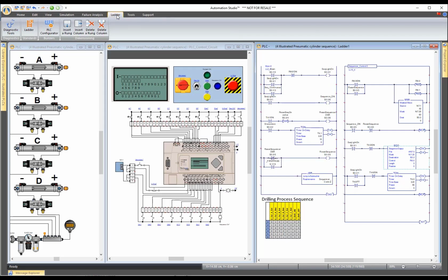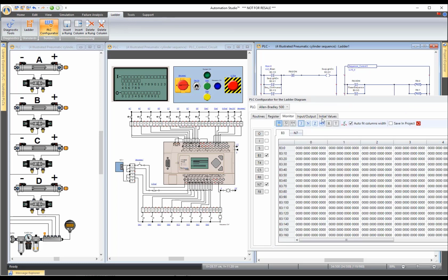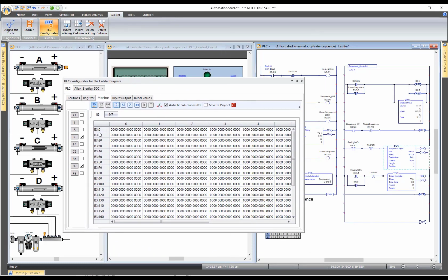If I go here in the ladder diagram, I open the PLC configurator. You see here is actually my sequencer. And I can see that my step 1, these are the bits I'm turning on, then step 2, step 3, step 4, and this is my mask here defining which of the bits I will take. Here it is pretty easy right now, we're just taking the 6th last bit. So this is the one that will be modified.